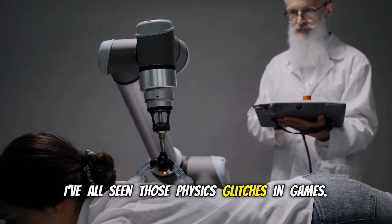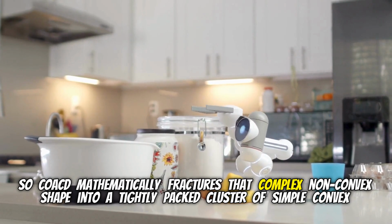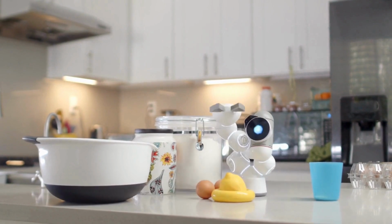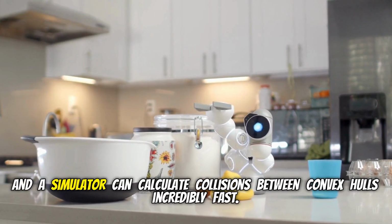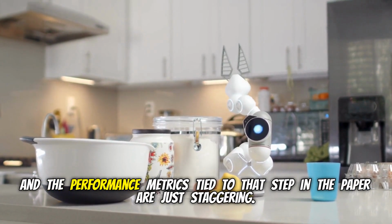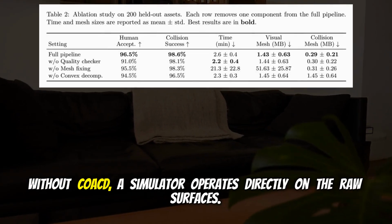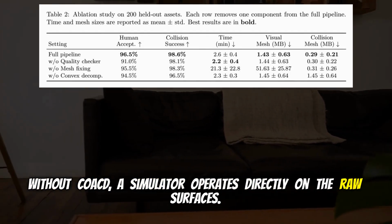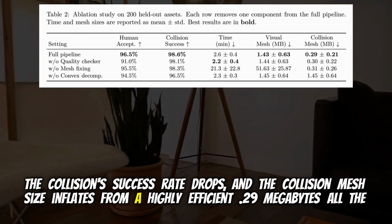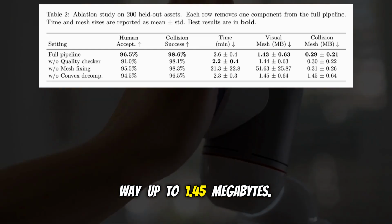I've all seen those physics glitches in games. Oh, exactly. So COACD mathematically fractures that complex, non-convex shape into a tightly packed cluster of simple, convex geometric primitives. Okay. And a simulator can calculate collisions between convex hulls incredibly fast. And the performance metrics tied to that step in the paper are just staggering. Without COACD, a simulator operates directly on the raw surfaces. The collision success rate drops, and the collision mesh size inflates from a highly efficient 0.29 megabytes all the way up to 1.45 megabytes. Wow, what a bloat.